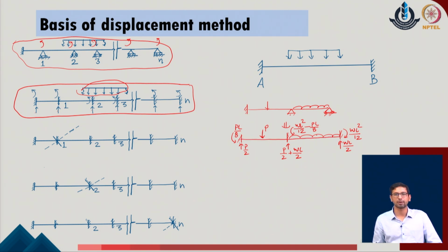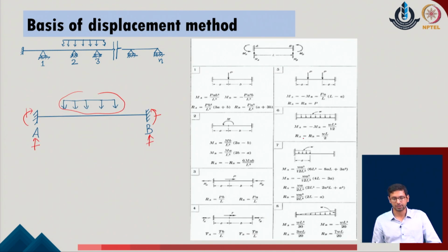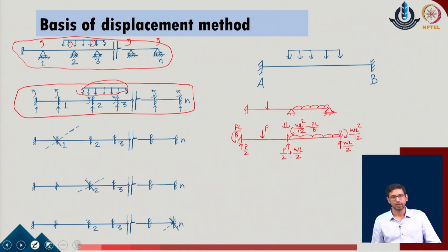So, with this idea in mind, I can understand that evaluating these system reactions for a fixed ended system is much easier, and for our help we already have a set of standard cases which are available to us. From these standard cases we can easily evaluate the system reactions for the fixed ended part. Now, as we do the process, we have calculated that the first system, which is the kinematically determinate system, has got all the reactions of the given system.